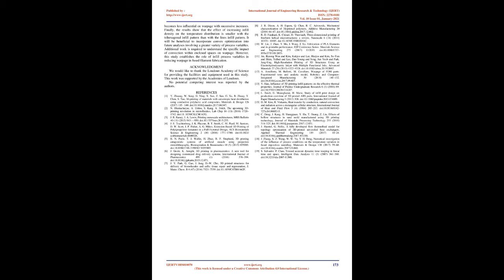6 Conclusions. With growing applications for fused filament fabrication in industry, the thermal properties of manufactured parts become critical in understanding the widespread problem of warpage due to part size. This study identifies that infill pattern and infill density are major factors on the isotropy of temperature distributions as well as the pattern of heat flow trajectories. Since increase in isotropy of temperature distribution reduces warpage, the results demonstrated that the choice of the trihexagonal infill pattern over the lines infill pattern reduces warpage significantly.